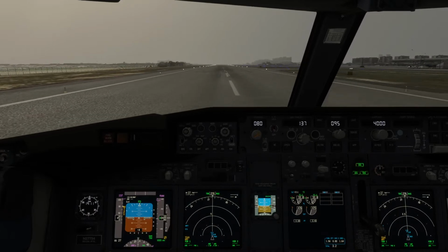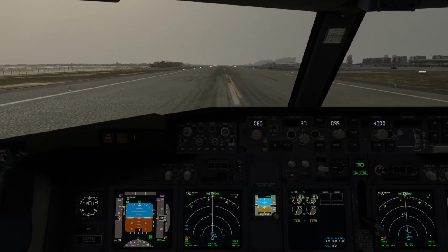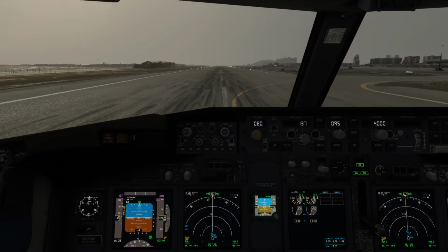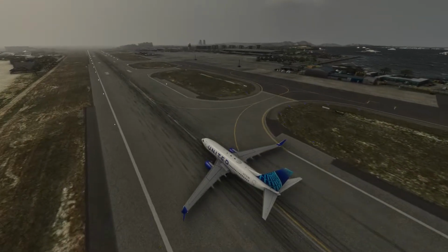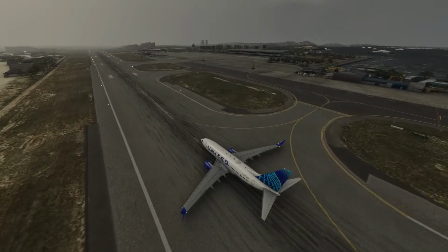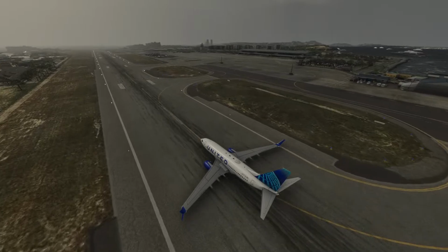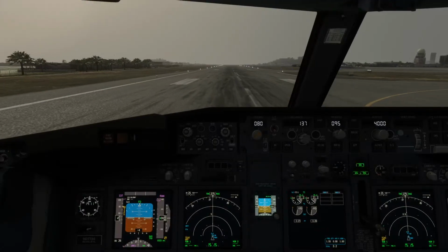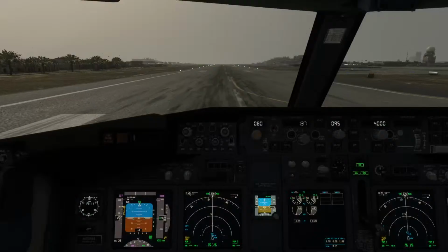And that's why actually my flare was not really good, because I was expecting to be lower on this approach. I was thinking maybe I'm not seeing it correctly, and then I waited a little bit to reduce the thrust and I floated a little bit. So I think we have some issues with PAPI. Most of the runways they are like this, so it's really good if we can follow the VNAV.